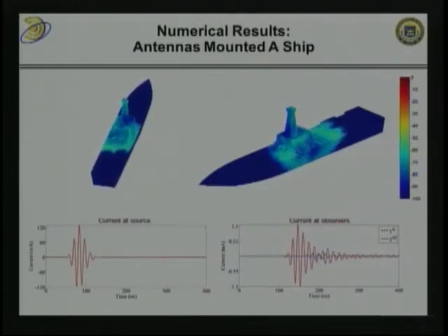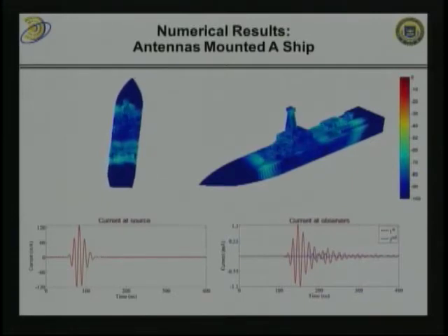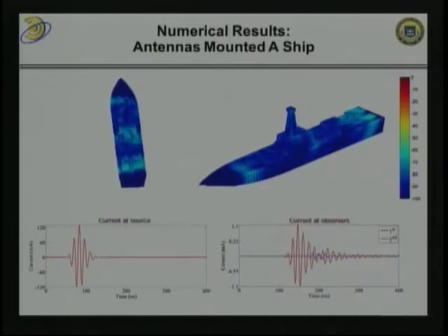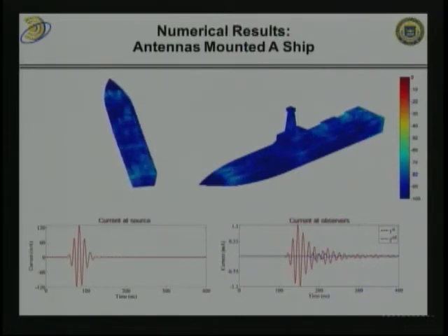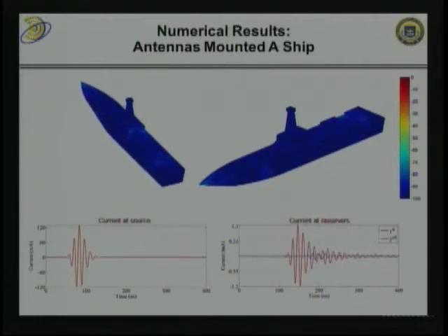Okay. One big advantage of these tiny integral equation methods, or in general of integral equation methods over differential equation methods, is that they're very, very accurate. So the dynamic range in our computation here is substantial. Often we get 4 or 5 digits in essence automatically. Okay. So here the field that is picked up, or the current that is picked up by the receiver antenna, which sits somewhere on the back there, is very, very small. Okay, a fraction of a milliamp. Again, to compute these things with that kind of accuracy, you would have a hard time doing it with finite difference solvers. With integral equation solvers, it's fairly easy.